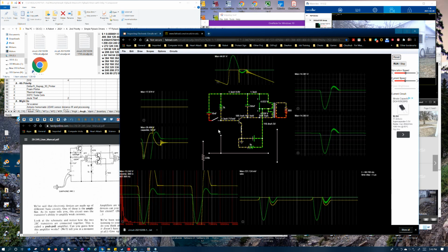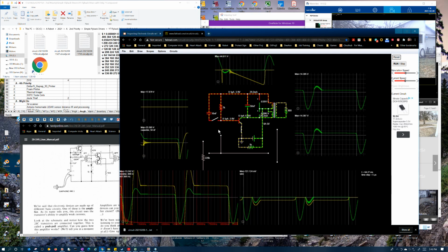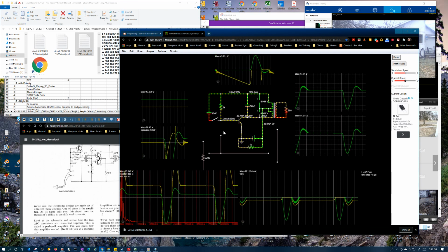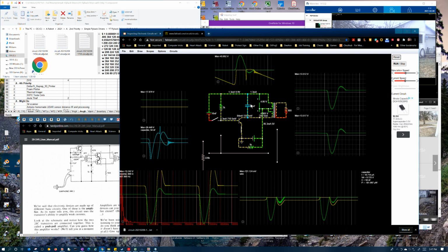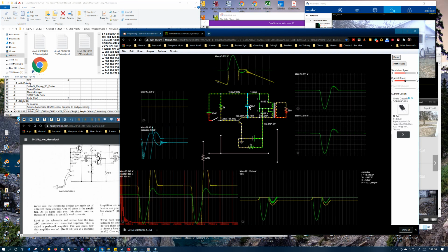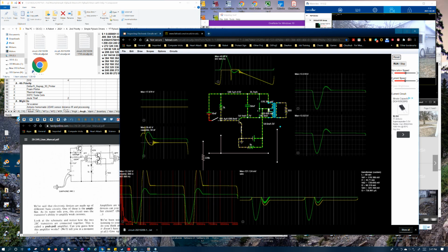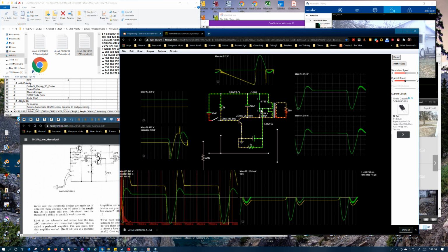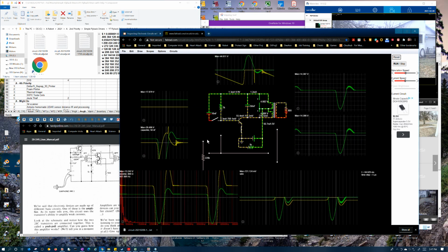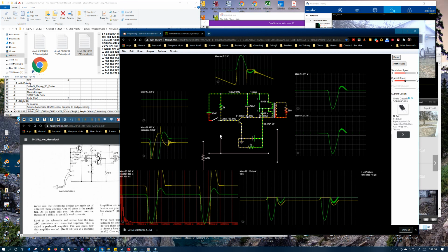That radically changes the frequency down to 600 hertz if I take that out of the equation, but it's still oscillating for some reason. I don't know if it's becoming resonant with this, because technically this is a tank circuit, so you'd think these things would oscillate without anything, honestly.